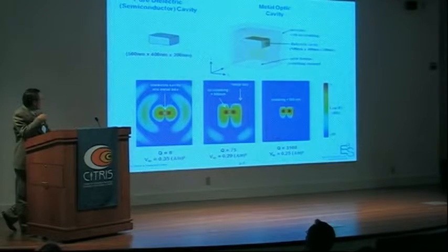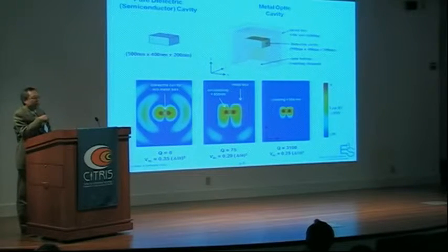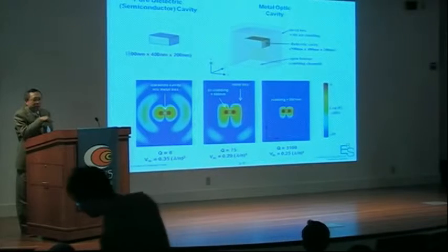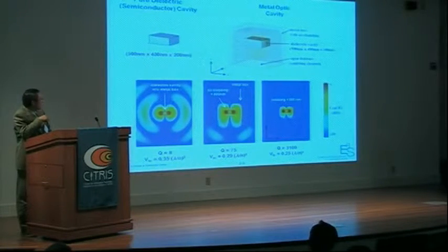Okay. So we have learned in microwave frequency that we can build a higher quality factor cavity by using metal enclosures. Same thing here, metal is very effective in stopping the radiation, as shown by the examples on the right-hand side, where we put this semiconductor emitter, presumably an optical gain material, and enclose it on all 5 sides except the bottom side with metal, and you see that we can almost completely cut off all radiation. We can also tailor the design to have a varying amount of light coupling to the outside world. So with this so-called metal optics optical cavity, we can progressively scale down the laser size.